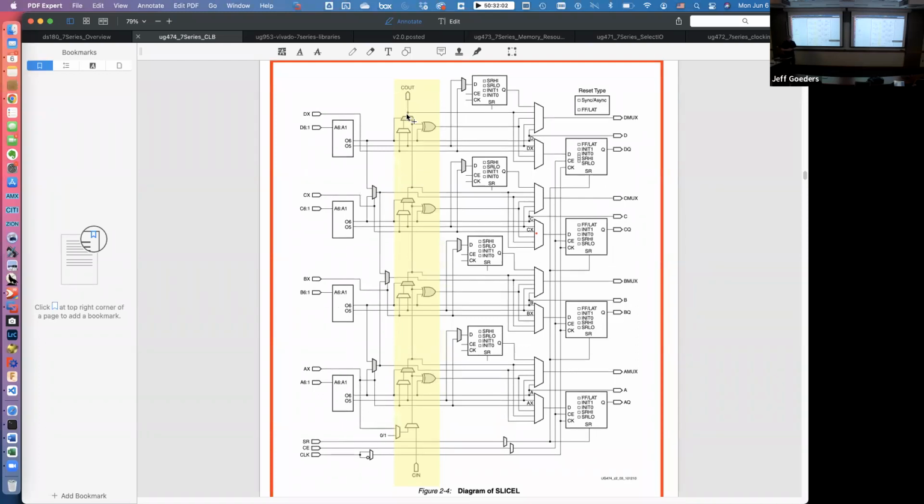It kind of looks like what we saw last time, but they grouped multiple logic cells together and they've added a bunch of other gunk to make life easy, right? Okay. Now, one of the things to notice is, look in the lower left. Notice that this clock signal, each flip-flop does not get its own clock. All 8 flip-flops in this slice share that clock. That makes sort of sense. But also, there's only one set reset signal, which means if you're using a flip-flop with a built-in clear signal on it, then all of the flip-flops in the entire slice have to use that clear signal.